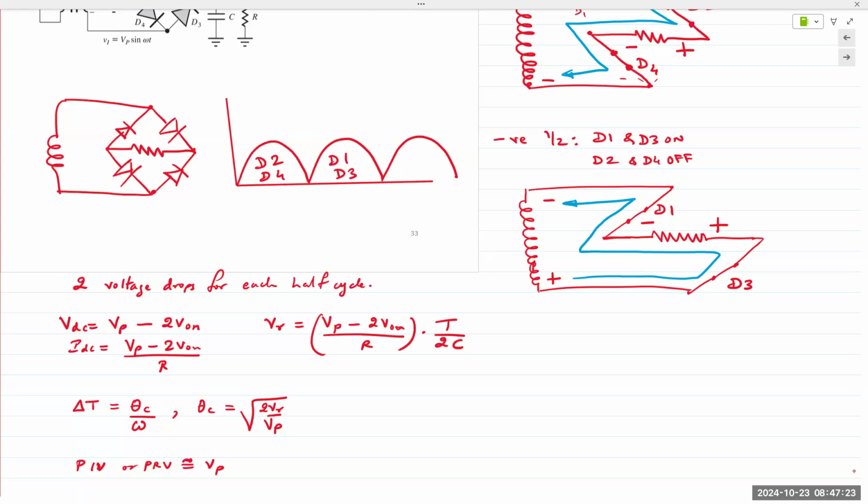All the mobile chargers that we have nowadays. The reason they are so lightweight is because you first take the 120 volt input and you directly rectify it into DC. So it's high voltage DC in a way. And then we convert that DC, we step it down, and then we convert it back to AC. And so when we convert it back to AC at a lower voltage, the size of the transformer is very small. And it's very high frequency. So you convert it to high frequency AC. Size of the transformer is small and it's lightweight. The transformers that we used in the lab yesterday, heavy. That's how all of them used to be.